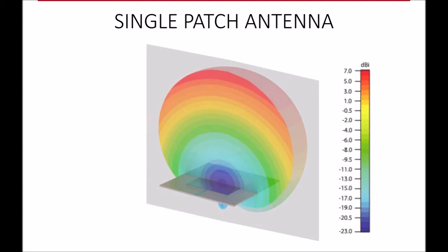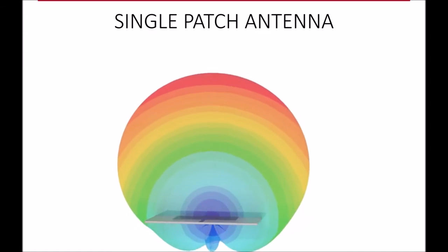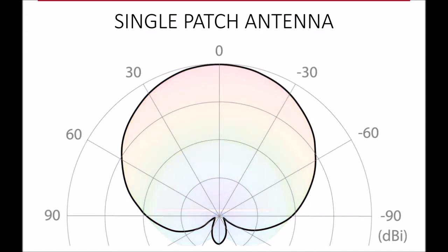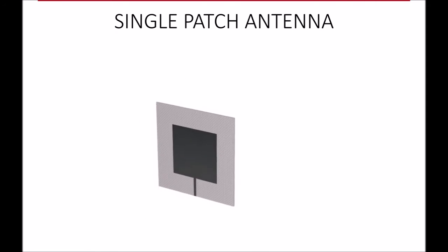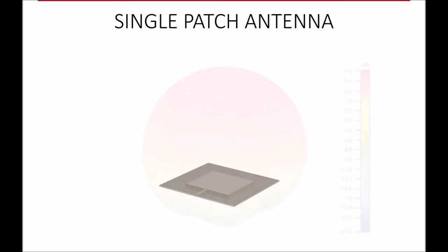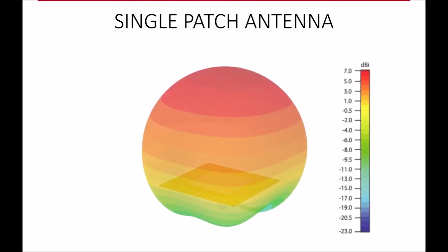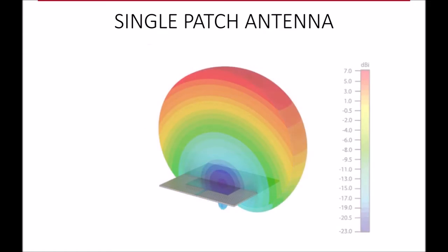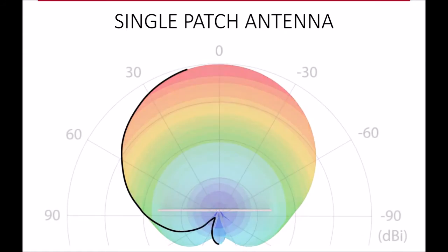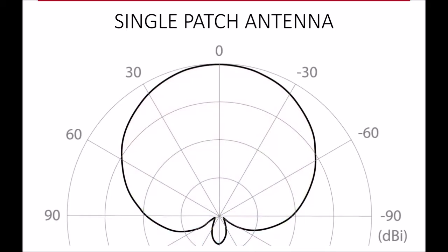And for WISPs, the 3D radiation pattern definitely makes more sense because the side lobes of the antennas are the root of the interference issues in unlicensed WISP networks. So the 3D radiation pattern will show you the whole information with all the side lobes, so you have the full image and know if you want to avoid or use the antenna you're looking at.